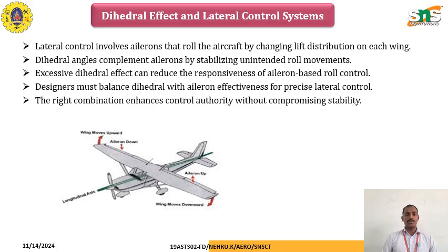Lateral control involves the aileron, which rolls the aircraft by changing the lift distribution on each wing side. So the dihedral angle complements the aileron by stabilizing unintended roll movements, while an excessive dihedral effect can reduce the responsiveness of aileron-based roll control. Coming to the designer part, we must balance the dihedral with aileron effectiveness for precise lateral control